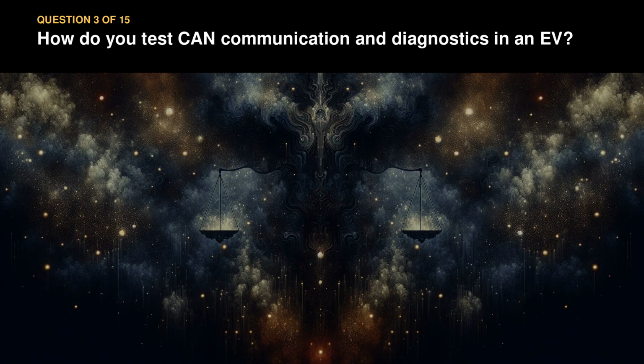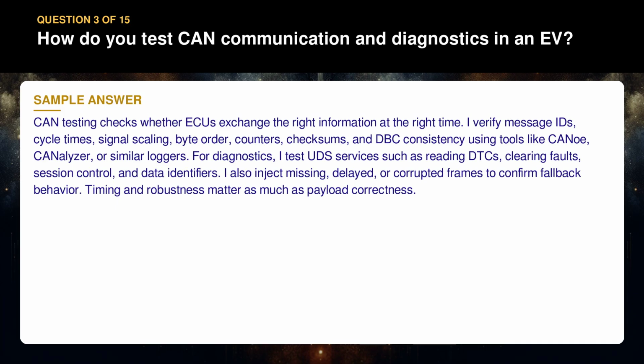Question 3. How do you test CAN communication and diagnostics in an EV? CAN testing checks whether ECUs exchange the right information at the right time. I verify message IDs, cycle times, signal scaling, byte order, counters, checksums, and DBC consistency using tools like CANoe, CANalyzer,